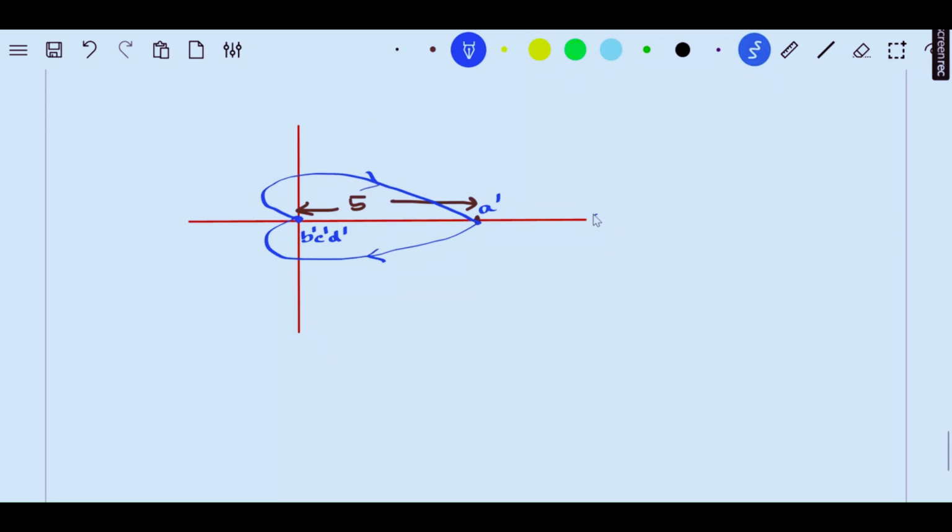So this is 0 degree, minus 90 degree. This is plus 180 and minus 180. This is omega equals infinite. Here omega equals minus infinity, and here omega equals 0. Okay, so this is the final trace which we obtain when we attach all 3 traces. And if you try to see in Nyquist, always minus 1 plus 0j, minus 1 plus 0j. This is the encirclement which we are trying to see now.